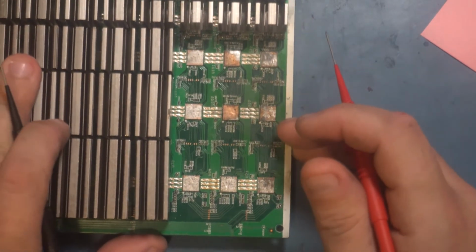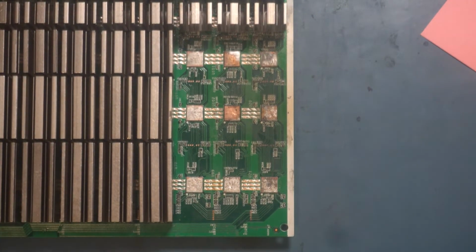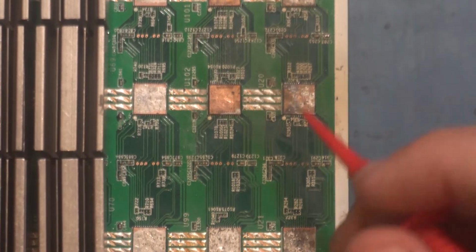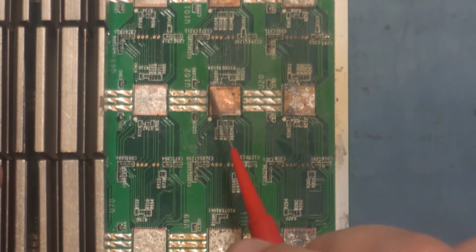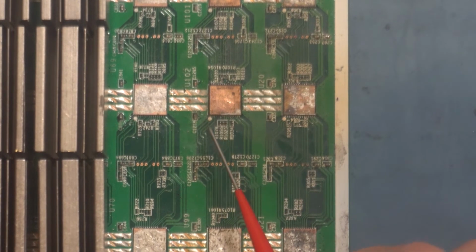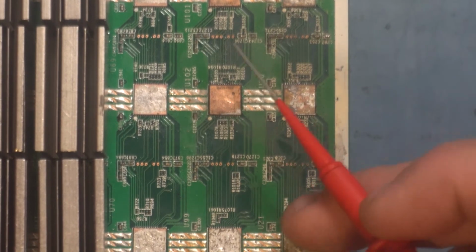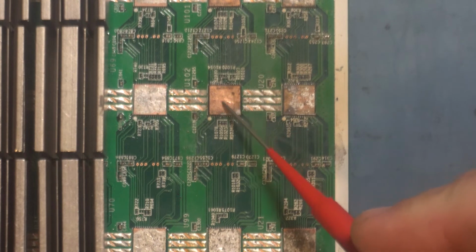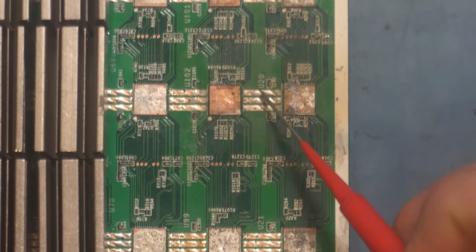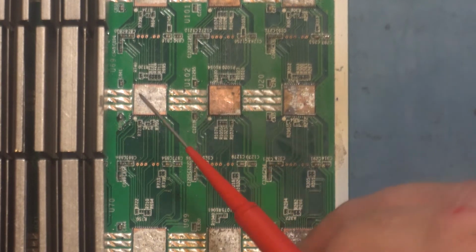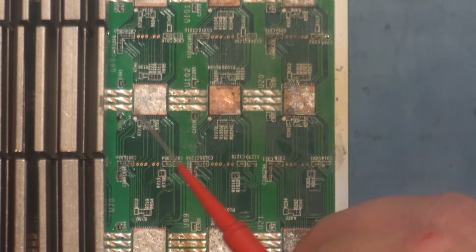And so there are other aspects to power distribution. A lot of people, especially when they start, think that the chip is powered by pins 15, 16 and 17, 18, which are the 1.8 and the 0.8 volt, but that's just not true. Those voltages are secondary power supplies that just enable some of the functionality in the chip. The main power, the main driver, is really through those 3 big traces that do the voltage dividing and carry the big power through from one domain to the next.